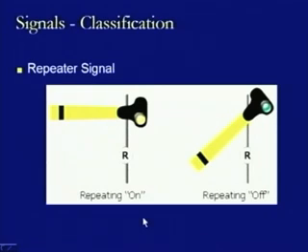Then this is another repeater signal which is provided in the form of a movable arm, and here it is yellow in color. Though this is semaphore type, it is yellow with the black band, and R is shown here. Again the conditions remain such that if it is in on position, it is horizontal, which is stop condition. If it is in inclined position, it means off position and proceed condition.